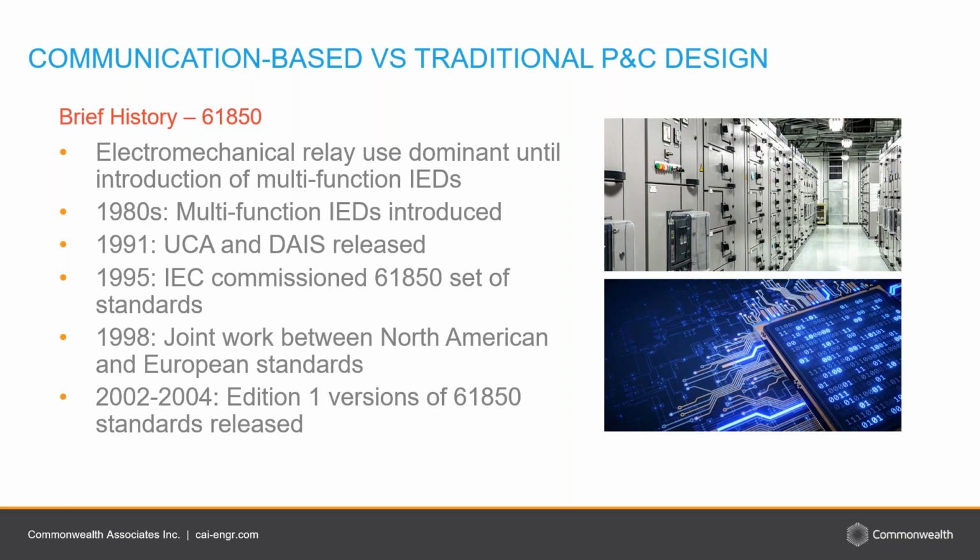Before I start talking about 61850 in earnest, let's see how 61850 came into being in the first place. Since early times, power system protection has been dominated by electromechanical relays. These relays function using a magnetic field produced by an electromagnetic coil when a control signal is applied to it. These relays did not communicate with each other or with the control center to provide data points like status information.